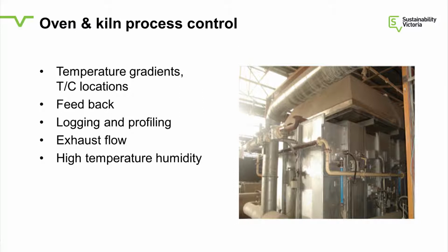So, improving the temperature gradient in this furnace, logging and profiling. Nowadays, most of the new instruments can log and profile the temperatures, and it'll give you a history of how well your furnace has performed. In the past, people were just flying blind. So that sort of not very expensive technology can help you fine-tune your piece of equipment.